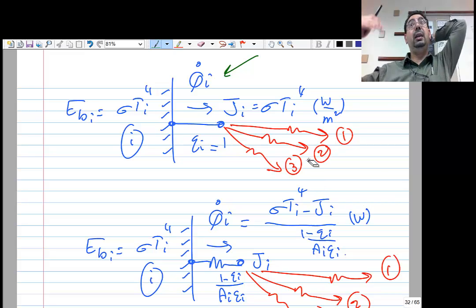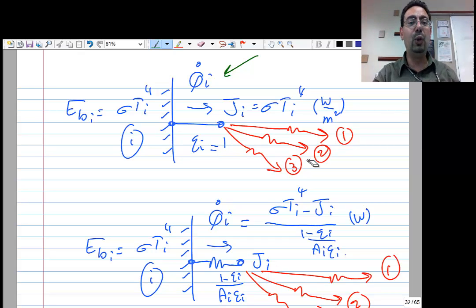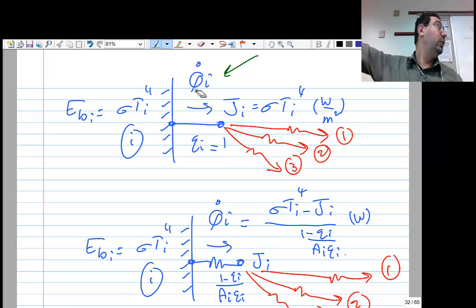the angle of course and the geometry, but at the end of the day we call this the view factor, the Fi1 and Fi2 and Fi3. So out of all the QI leaving the flame in the corner of the room, how much of that heat will hit the curtain of the window and the carpet?